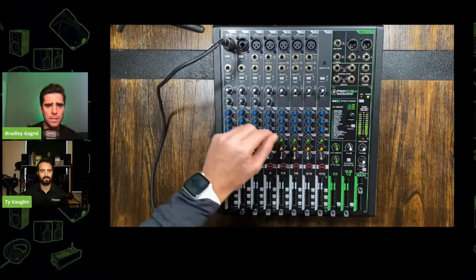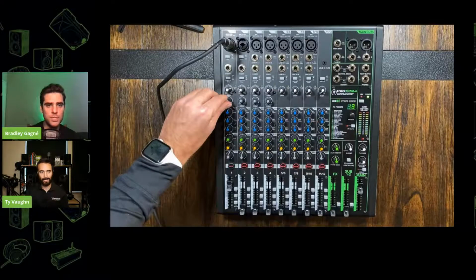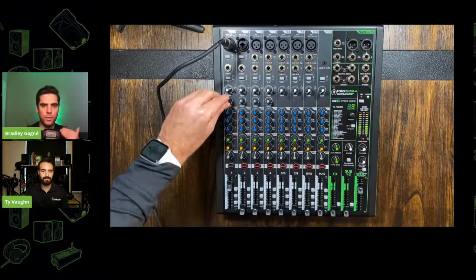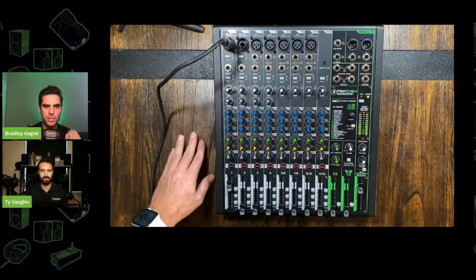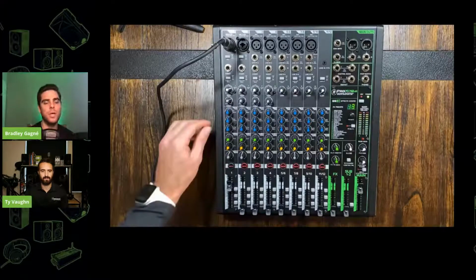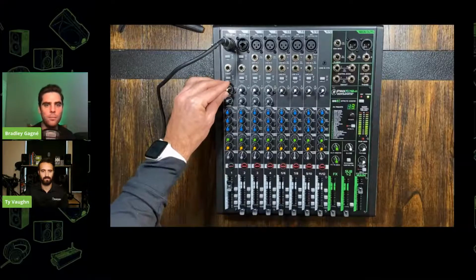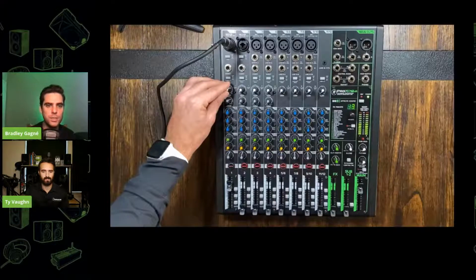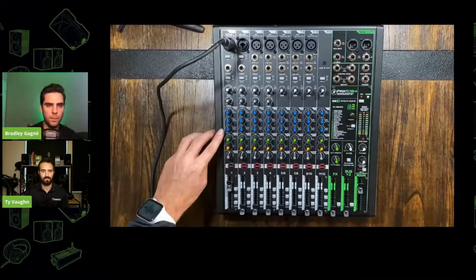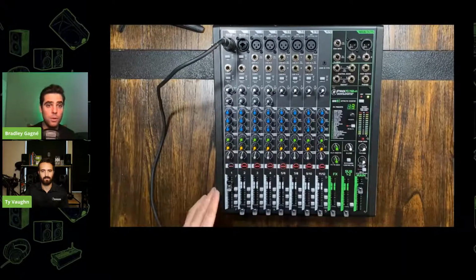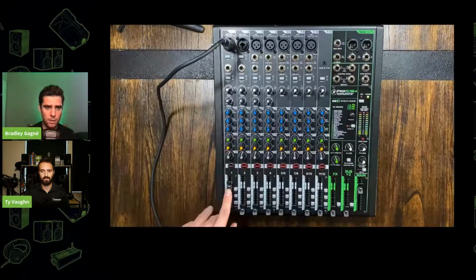Also, the compressor right here will set that threshold. If we're just tapping out at 0, we can crank up that compressor, level it out, and without adjusting the gain, compress the signal a little bit. That can help with bringing it down right at that 0 range, or tapping out before we clip over 0 dB. So going into the computer, you definitely want to set it up like that. Just make sure you're below 0 dB, and it's really that simple.